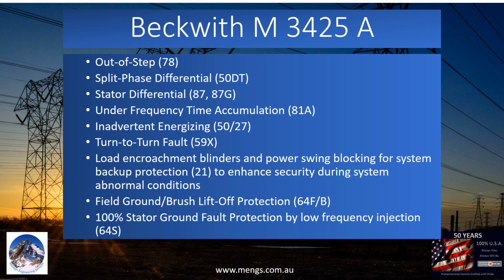Out of step. Split phase differential. Stator differential. Under frequency time accumulation. Inadvertent energizing. Turn-to-turn fault. Load encroachment blinders and power swing blocking for system backup protection, to enhance security during abnormal system conditions. Excitation ground protection. 100% stator ground fault protection by low frequency injection.